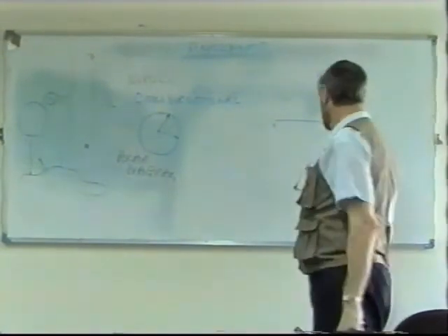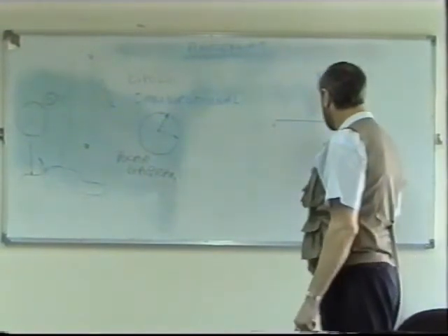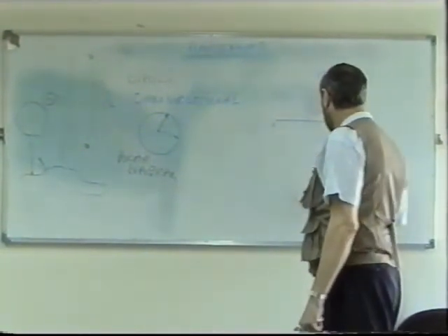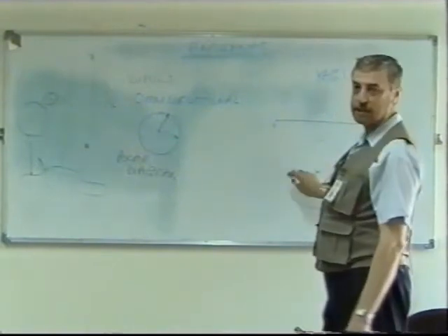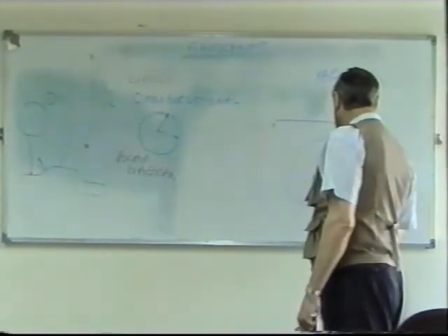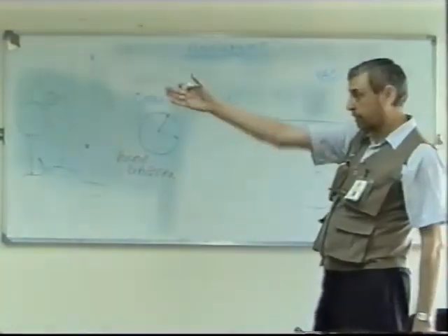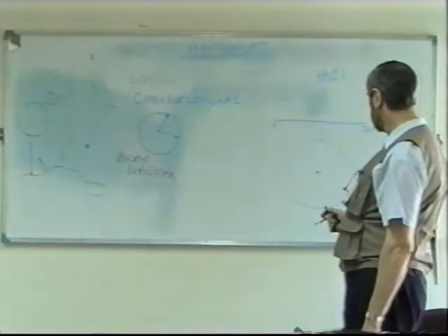Well, first of all, let's say we put a Yagi up in the middle of a field. Again, we've got our vehicle moving around with a receiver to receive the strength of the signal. There'll have to be some point where we say, right, there's our 0 degree point, which is usually the point where you're pointing your antenna.